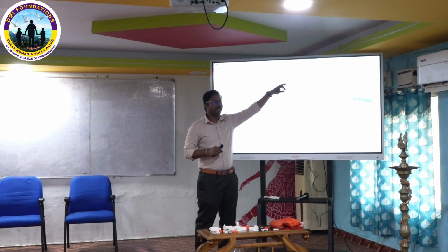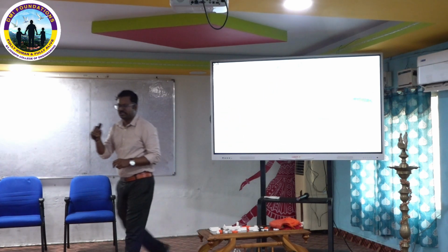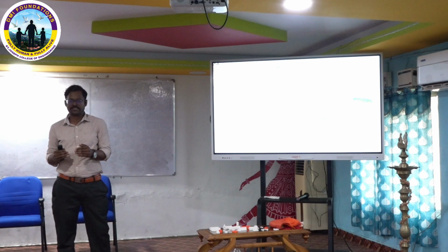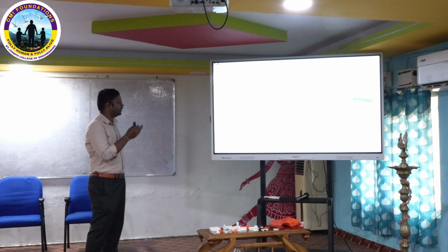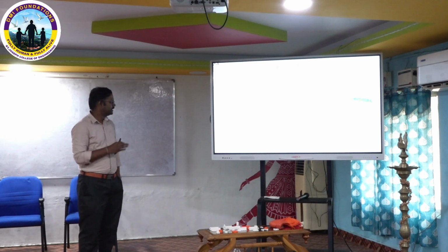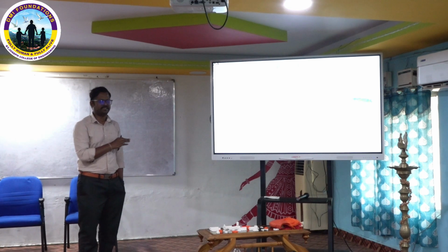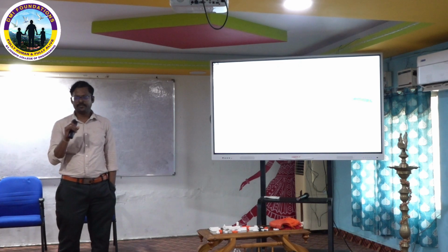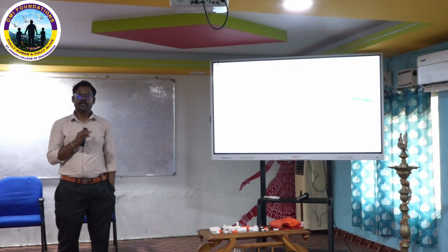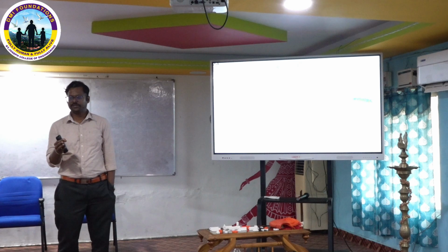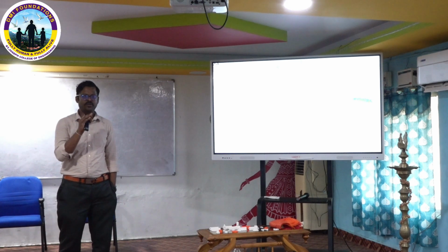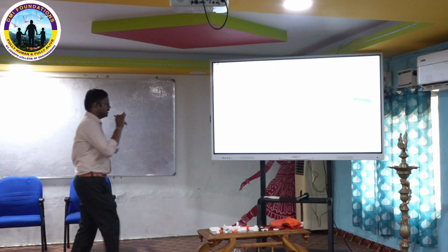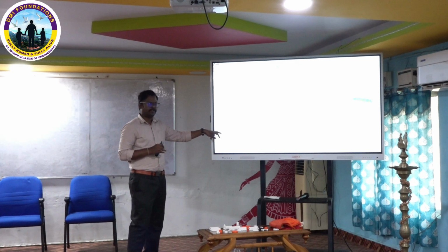So here I have to fix x equal to 0, y equal to 0, and only in the z direction I have to give how much distance it should compress. These are the things I have to give as boundary conditions. Then the next step is the analysis step, which is nothing but what kind of analysis you are going to do: explicit, dynamic, static. There are different types. In that, which type is suitable for your lattice structures and your environment study? That kind of analysis type you have to give, then run the simulation.